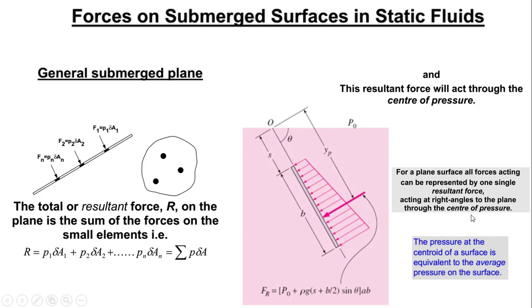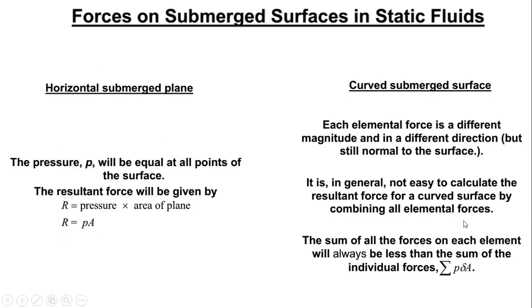Center of pressure is defined as the point where the resultant force acts. Now if we look at a horizontally submerged plane, we know according to Pascal's law that the pressure acting on this plane is going to be equal at any point, provided it's a continuous fluid.